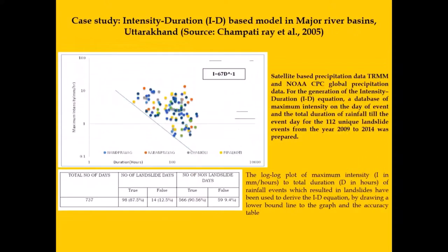But mind it, till now what we have discussed is all only about the amount of rainfall in millimeter. But what about the duration of rainfall? Suppose 50 mm rainfall happened in the last 2 hours, or 50 mm rainfall happened in the last 4 hours, or in the last 8 hours. All these will have different impacts on landslide occurrence. So that's how duration and intensity both are important. Intensity is basically millimeter per hour, and this axis is my time.